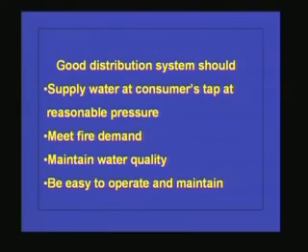It should meet the fire demand. It should maintain the water quality. Like when we supply water to the consumers from the treatment plant, we add chlorine at the treatment plant, but the residual chlorine at the tap level is more important for the health of the consumers. So, what is happening to the water quality in between is also very important.